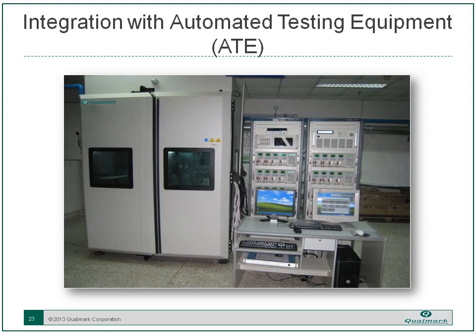The next step you'll need to worry about is getting the system integrated with your automated test equipment. Qualmark provides a couple of software packages for their controller that can help you link the two together. We have a package that provides you with a set of LabVIEW drivers that will communicate directly with the PLC controller and the control panel on the chamber, and allow you to write software that essentially eliminates the computer interface that you normally look at when you're running the chamber, and incorporates that entirely into your ATE software.